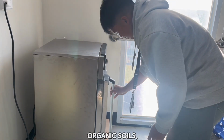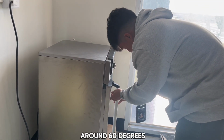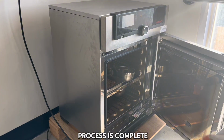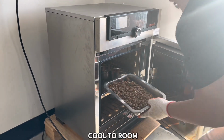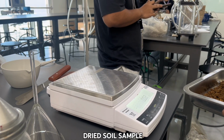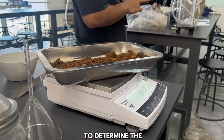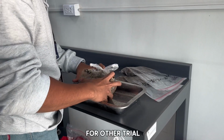For peat or organic soils, use a lower drying temperature of around 60 degrees Celsius and extend the drying period to avoid burning the organic matter. Once the drying process is complete, carefully remove the container from the oven and allow it to cool to room temperature. Then, weigh the container with the dried soil sample and record the final constant mass as W3. These measurements will then be used to determine the moisture content of the soil sample. Repeat the process for other trials.